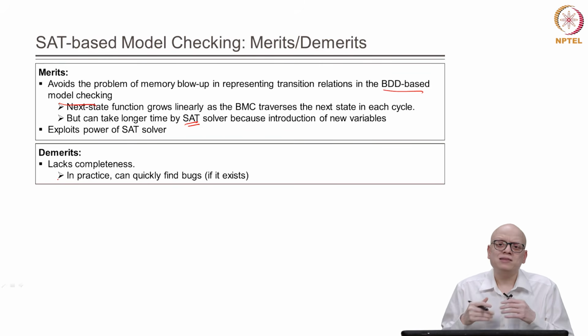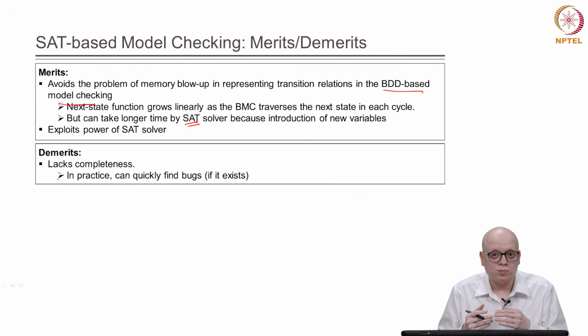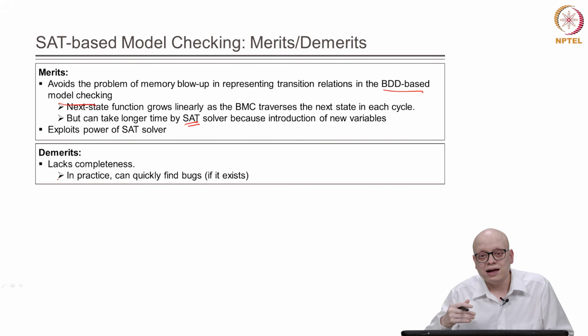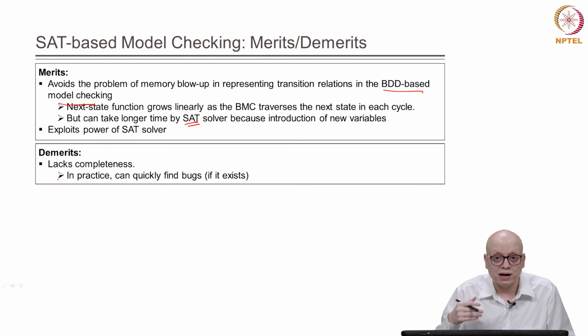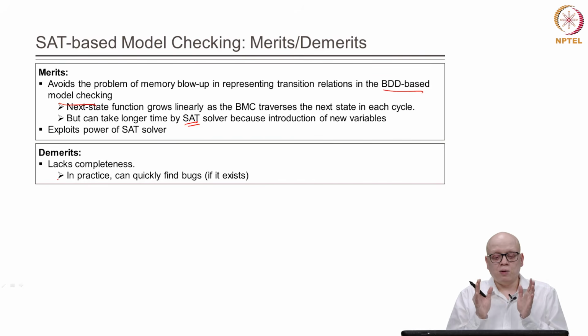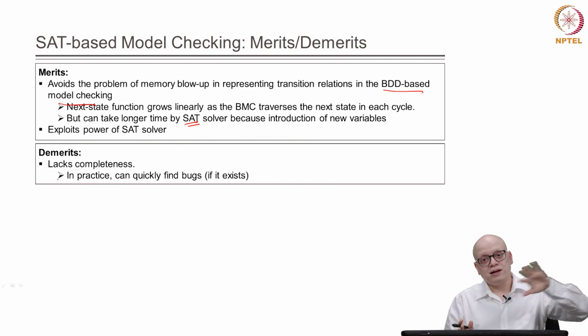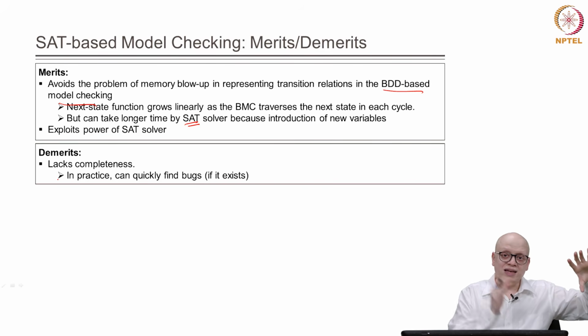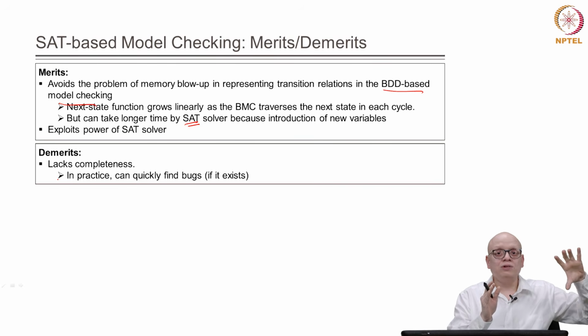So, where is the application of bounded model checking? In practice, it is used to quickly find bugs which we, as designers, cannot find easily, for bug hunting. Why is it useful? If we have done BMC up to say 5 clock cycles, till 5 clock cycles it is considering the entire input space for a given property. So, if there is a failure within 5 clock cycles, we will get that failure.